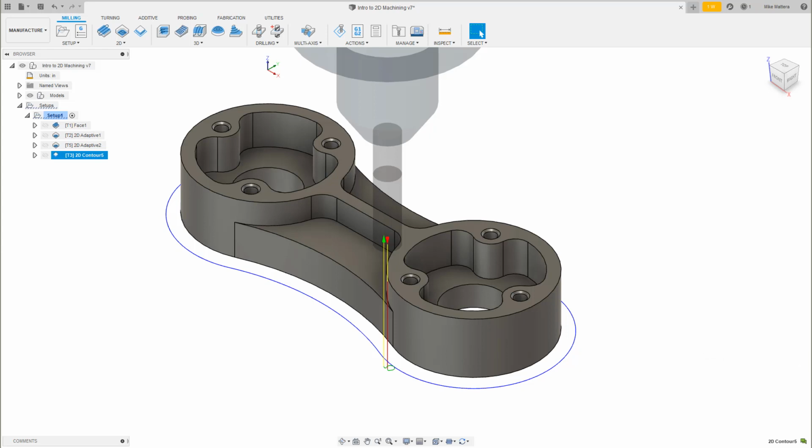In this lesson, we learned about the 2D contour finishing strategy. Selecting a new tool, cutter compensation, the potential to take multiple cuts in XY and in Z, using the lead in and lead out to blend onto the profile. Press Ctrl S to save the part, Command S on the Mac.